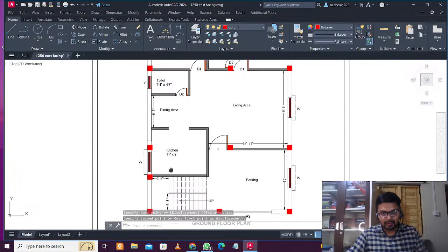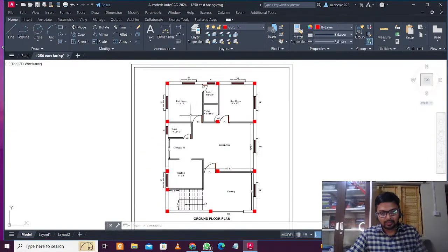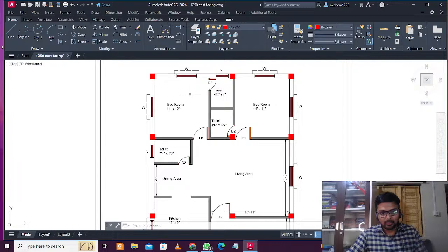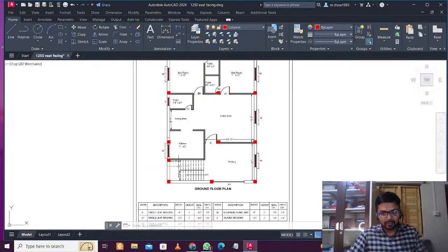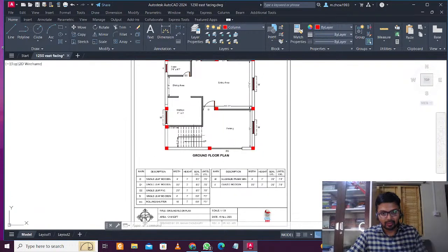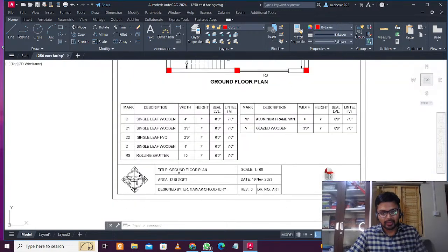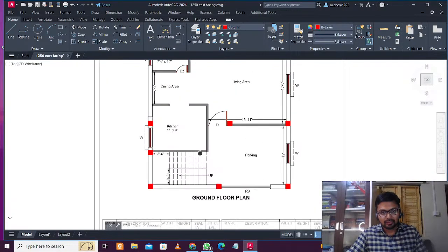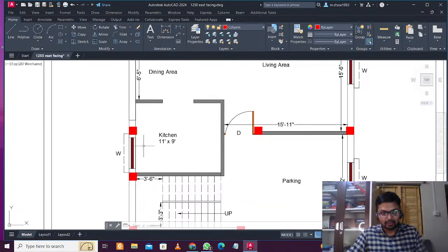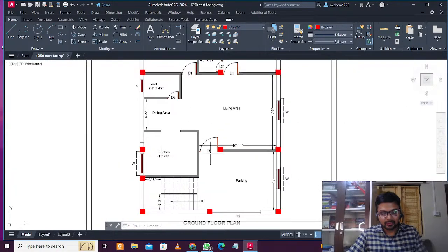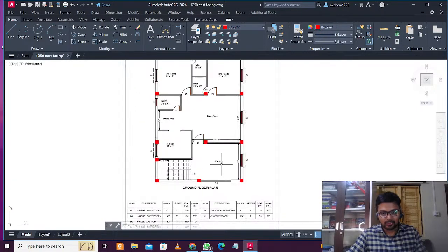These 2 columns will be rather very close, but you have to give this due to the staircase. So you can see how many columns there are. 3, 6 and 9, and then 12. So 12 columns each of 3, and then 13. So 13 columns, and the total square feet is 1300. So around 1 column every 100 square feet, or a little bit more than 1. So it is okay for now, the column positioning. And once this is done, okay, the column positioning is done.